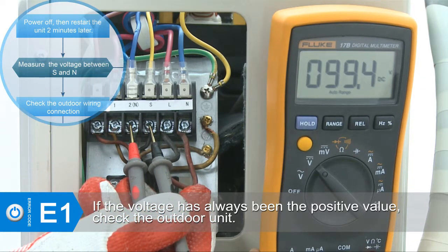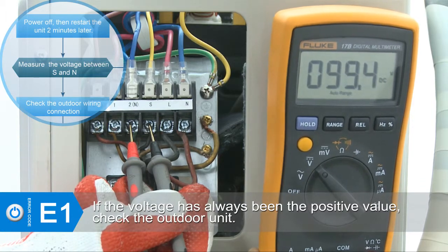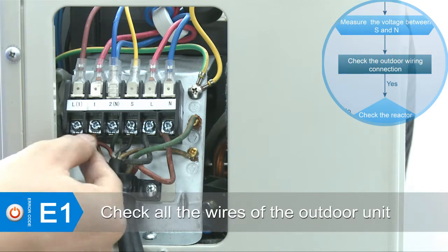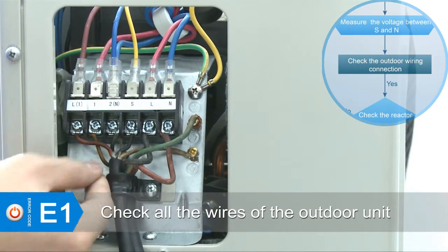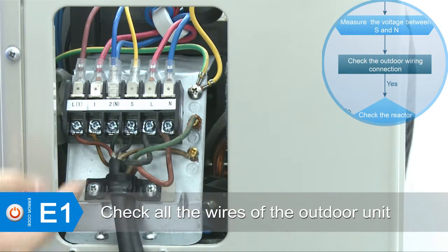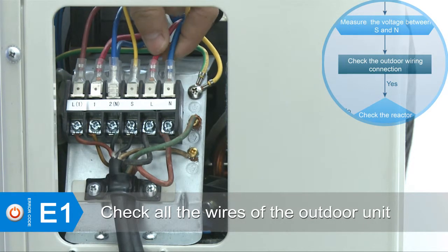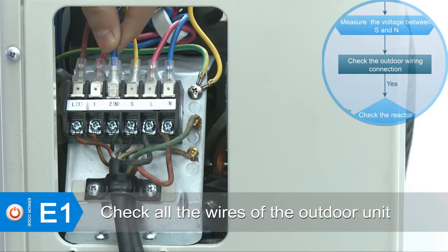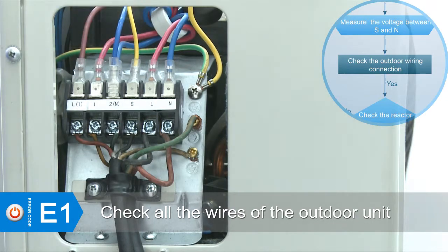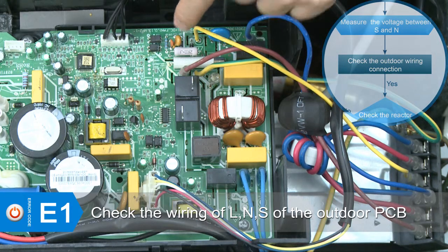possible malfunction may have occurred on the outdoor unit. Main attention should be paid to the outdoor unit. Check the wiring of the outdoor unit, which includes the power wires and the connecting wires between the indoor and the outdoor unit. Check the wiring of L and S of the outdoor PCB.